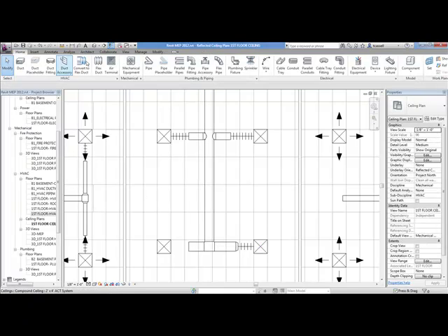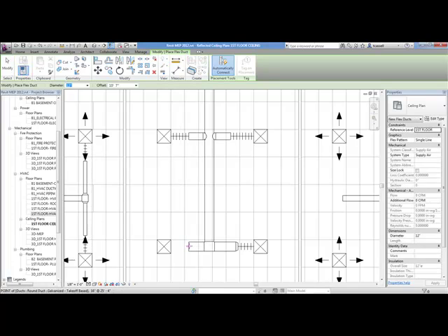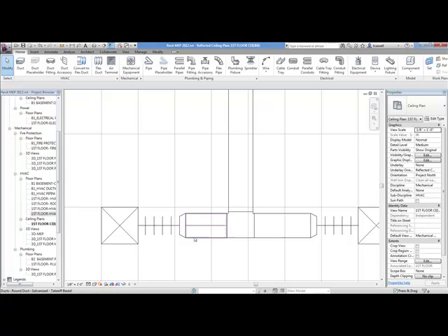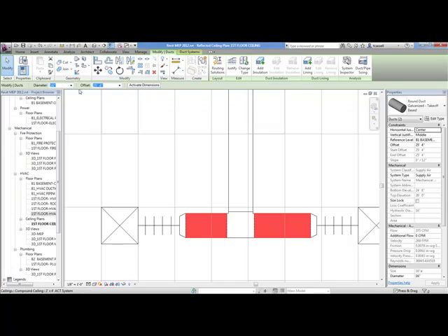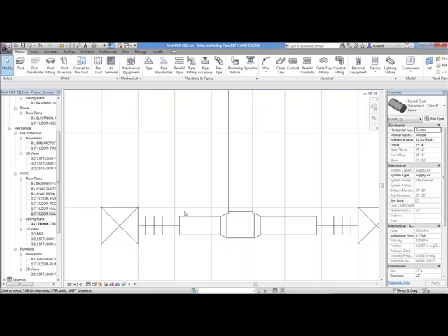All right, what you're noticing that it's doing on this last duct is I ran 14-inch duct at the end. So Revit's instantly seeing that, hey, in order for this to work, you need a reducer. So it's automatically putting a reducer in for me, so that way this duct works. Well, I'm going to say, you know what? This was actually supposed to be 12-inch duct anyway, so I have to shrink that.